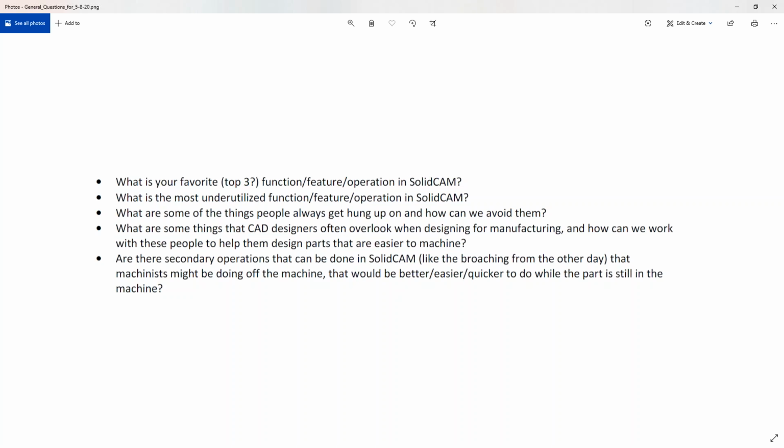Now, granted, if you have a very long cycle time, and I'm using my experience from a shop that had close to 60 CNC machines. Some cycle times were 30 seconds. Some cycle times were an hour. So if we had an hour-long cycle time where we saw an operator sitting on his butt and playing on his phone, then we would eliminate those deburring operations in the machine. So the operator down on the floor can be deburring while it's being done.